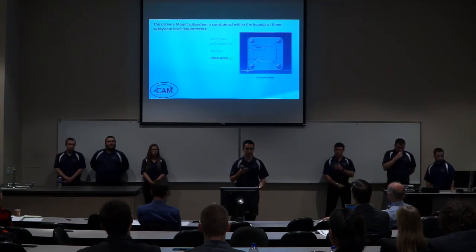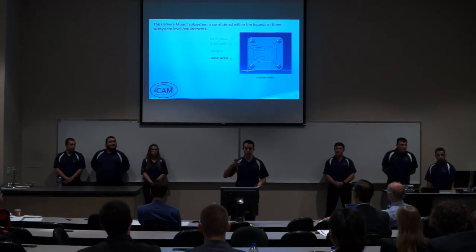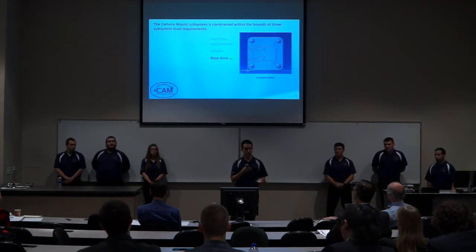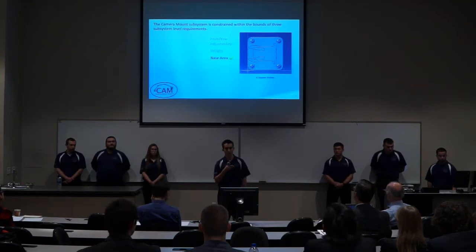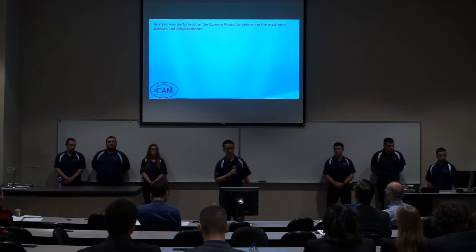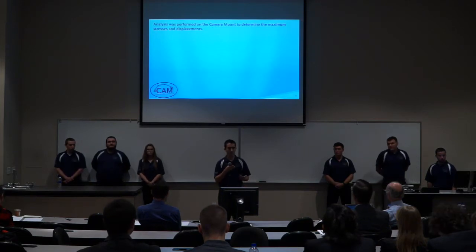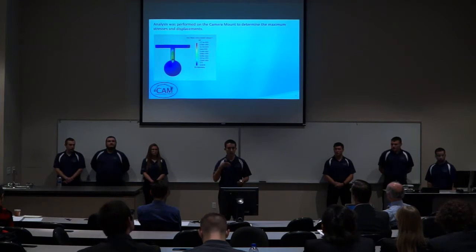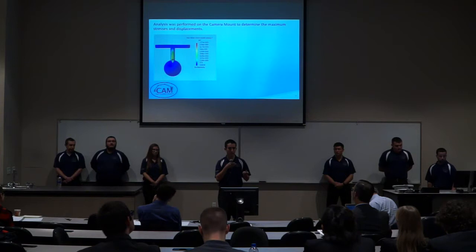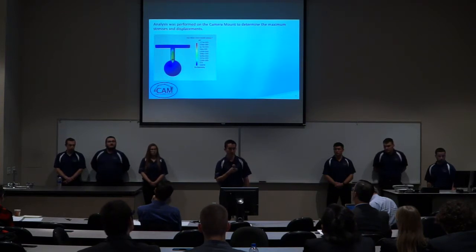And then we have a base area because we didn't want too cumbersome of a design for the stored configuration. We limited ourselves to 5 square inches, and right now we're coming in at 4 square inches with our current design. We also performed some stress analysis on this subsystem just to make sure that it would maintain that 20-pound force requirement. In this picture, we held the ball joint in place and applied a 20-pound force axially at the point most likely to fail, which was that cylindrical connection point between the ball and the plate.